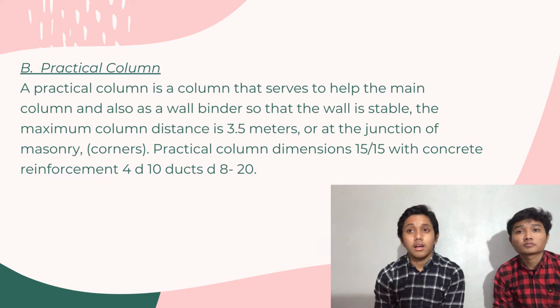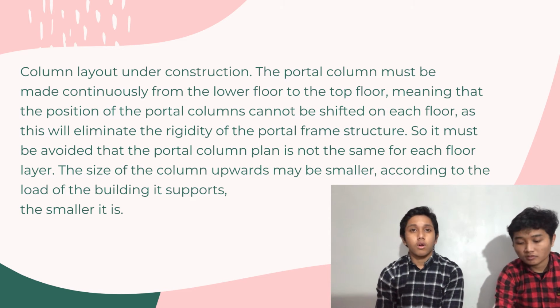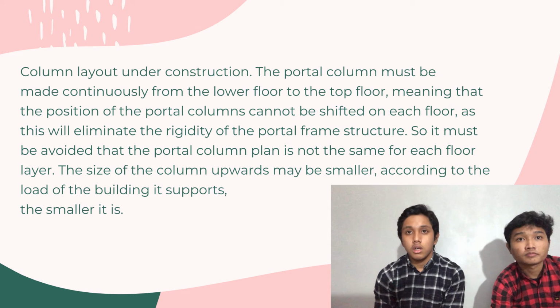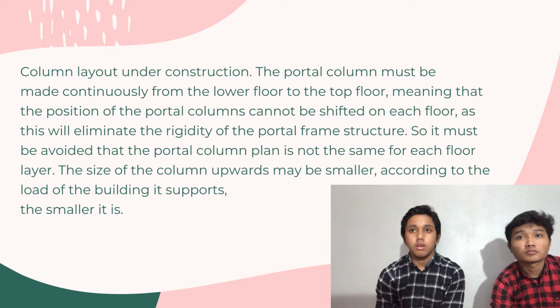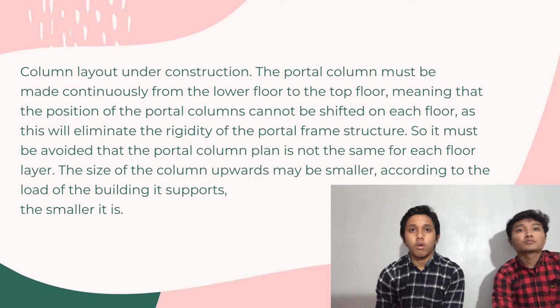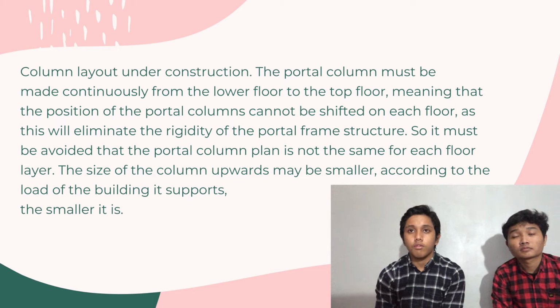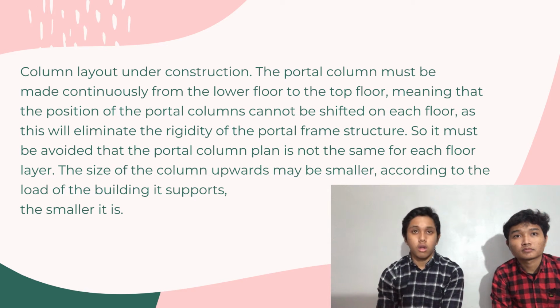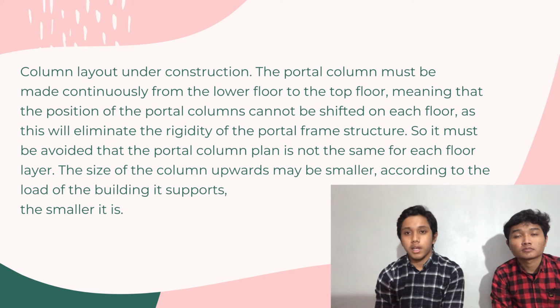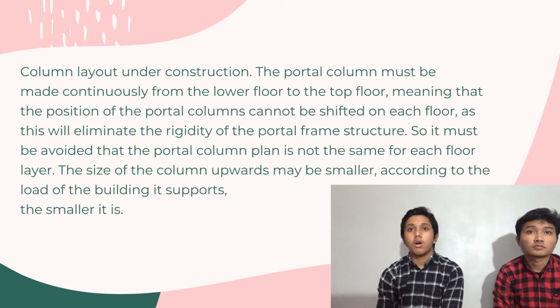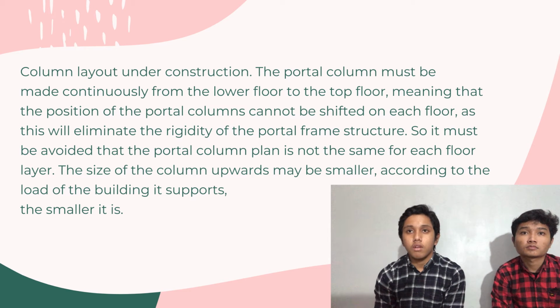D8 until 20. Column layout under construction. The portal column must be made continuously from the lower floor to the top floor, meaning that the position of the portal columns cannot be shifted on each floor, as this will eliminate the rigidity of the portal frame structure.